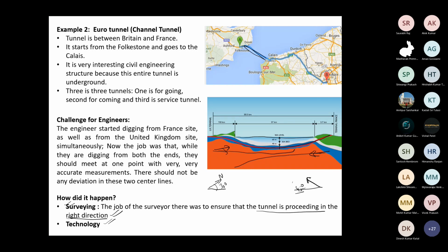Yes, sir. There is some instrument. You cannot just go and do something by yourself. There are very sensitive theodolites, accurate to 1 second. This is called a gyro theodolite. It is other costly equipment, but it is possible, and you can maintain the direction with that.